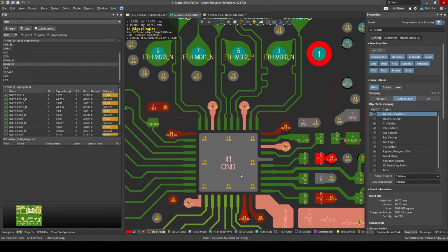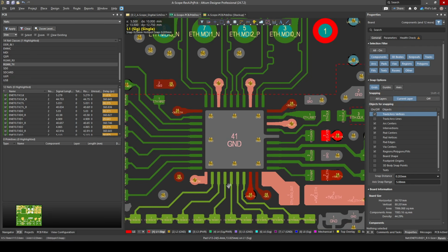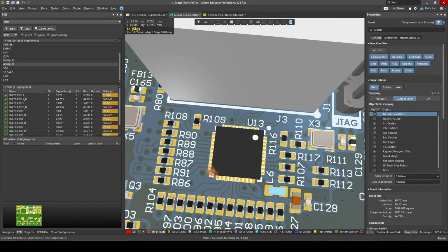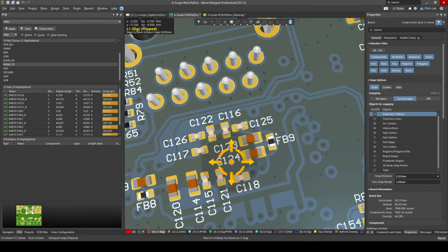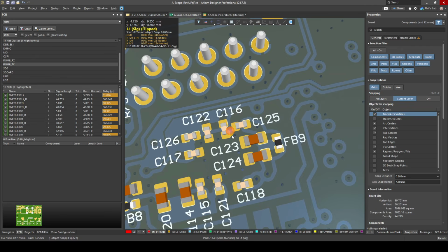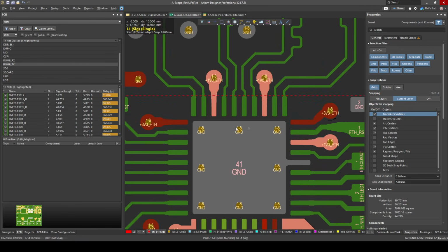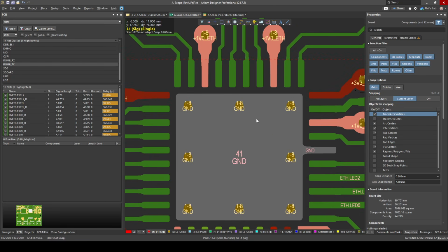Just to briefly cover all the bases, of course, for this QFN style package, because we are fanning out most of these pins, having decoupling capacitors placed right around this package on the first layer might be a bit difficult because of all the signals we have. So actually what I did, and what I like to do oftentimes if I do double-sided assembly, is place my decoupling capacitors on the bottom side. So the way I do this is I have, of course, my exposed pad. I have the grounding vias internally. This is both for electrical and thermal reasons. These are my ground return vias.